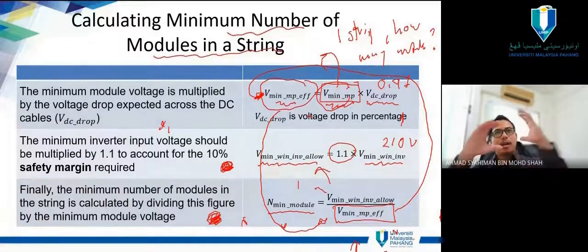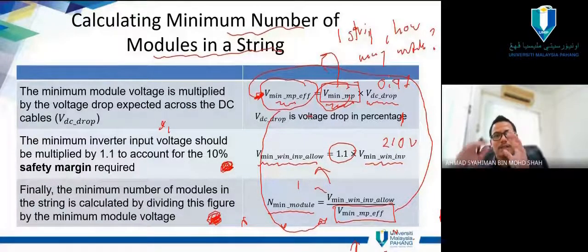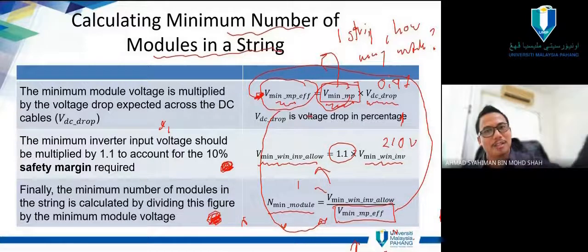Okay. Output voltage of the modules, whoever designs for PV, whether standalone or anything, the inverter has its range of input voltage, and you must be in that range. If lower than that, the inverter will not turn on. If the inverter does not turn on, nothing will happen. No energy generation, no energy transport, no energy export. The inverter is designed based on the minimum voltage. If the input doesn't meet the minimum number, it will not turn on, even for 30 years.